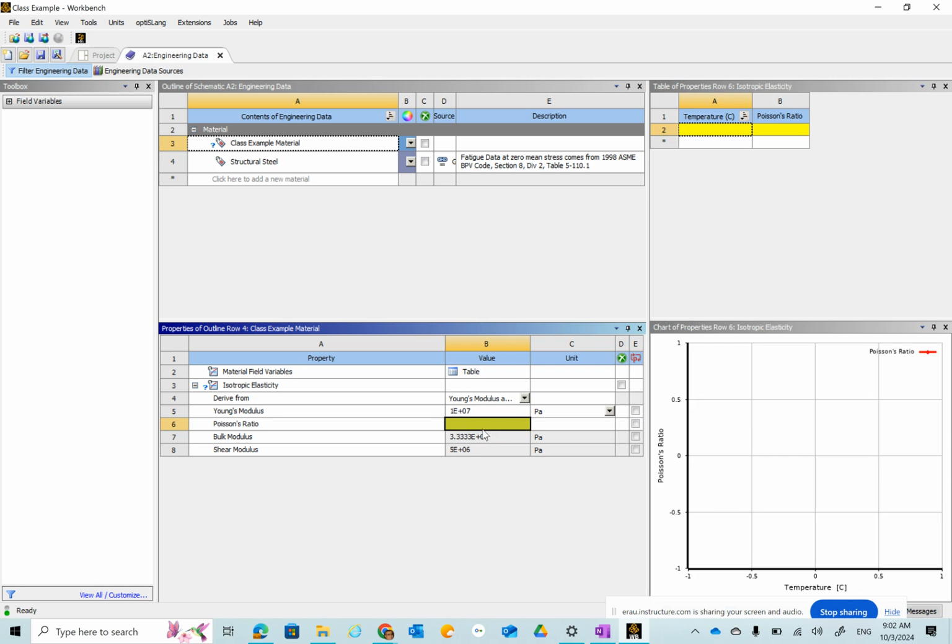And one thing you would notice, the units. I am inputting the units, and this is my responsibility to select the correct type of units. Our problem is in US customary units, and by default, ANSYS picked SI units. So before I move any forward, we need to learn how to fix that.